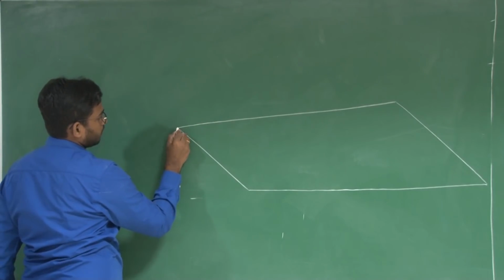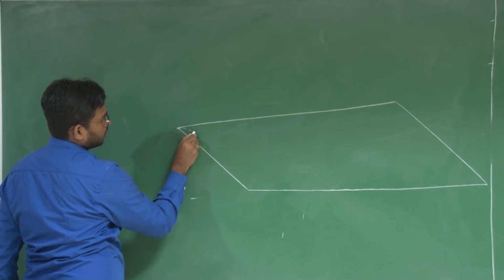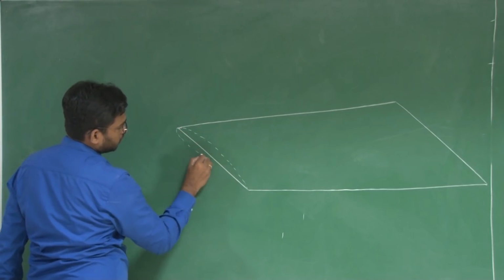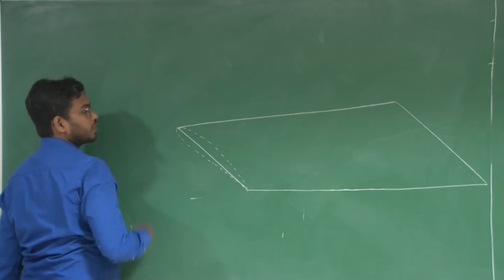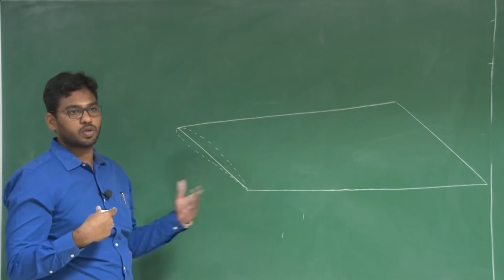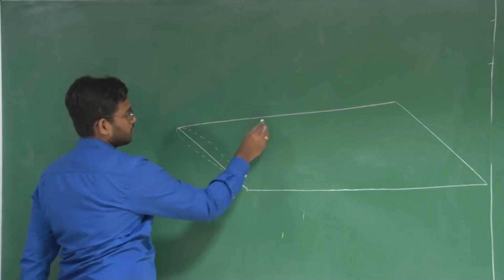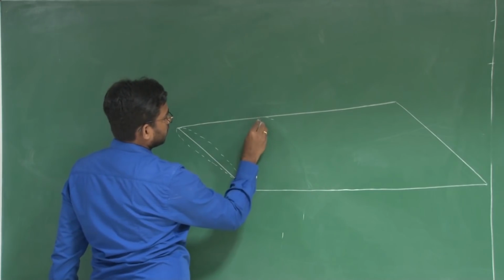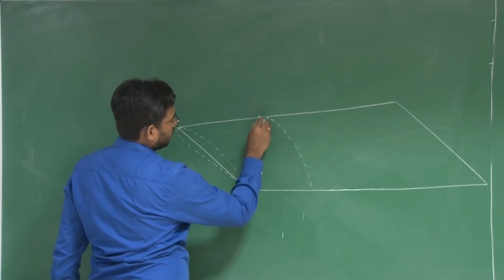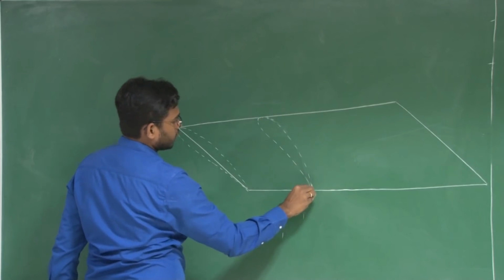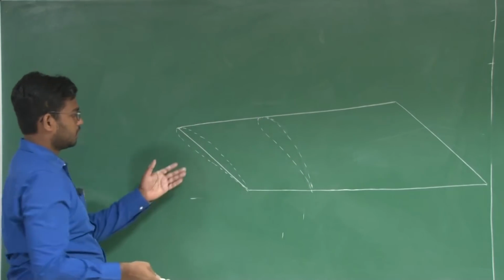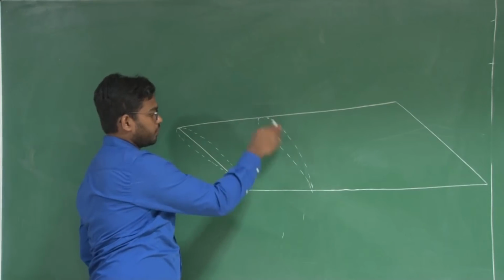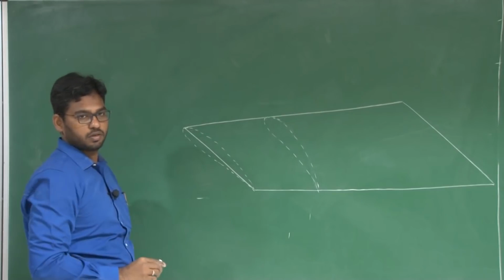Now, at each and every location you have aerofoils. Let us say there is no twist, neither geometric nor aerodynamic twist. So we have the same aerofoils oriented in a similar way, like the orientation of this is exactly what we have as the root chord. That means the chord of each aerofoil lies in the same plane.